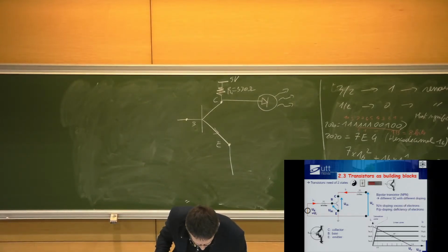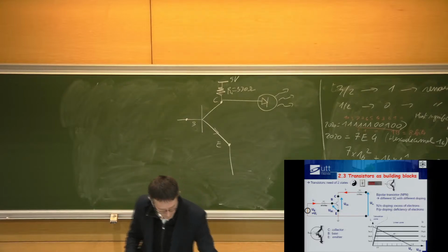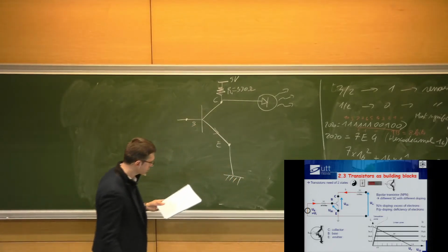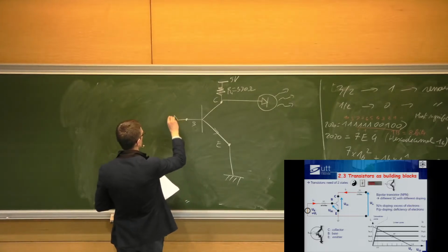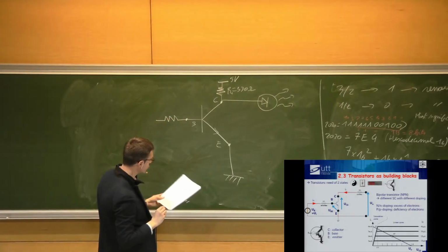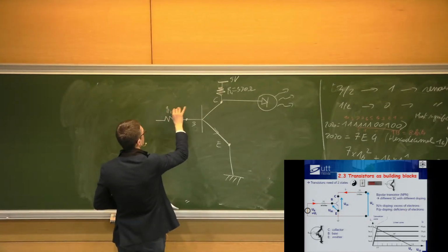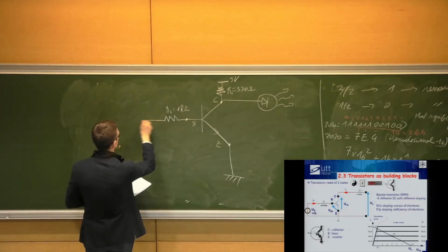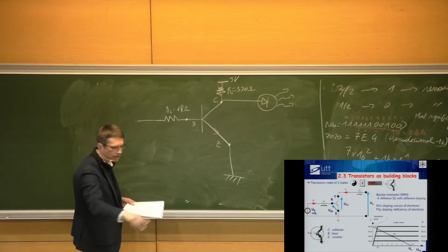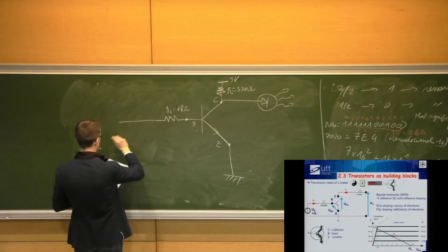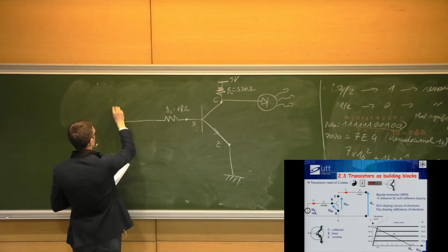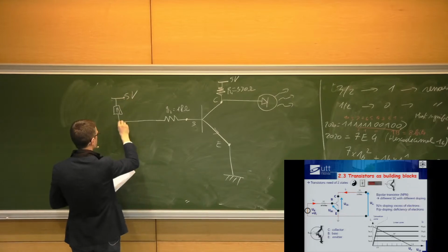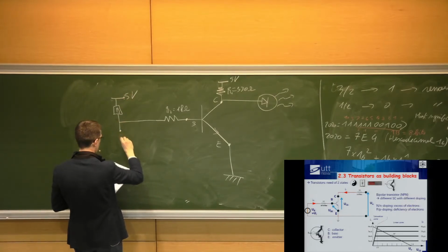That would be this one, number 5. For now, everything's off. The emitter is linked to the ground. Then at the base, we've got another resistor, in this case R2 equals 1 kilo ohm. This is linked, inside the circuit board, to another resistor that I don't know the value of, but it doesn't matter, and it's powered, and then there's an interrupter, a switch.